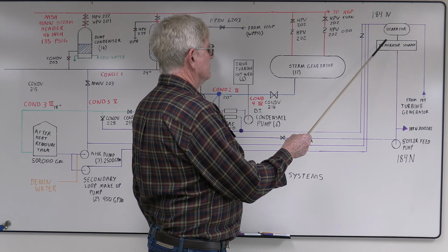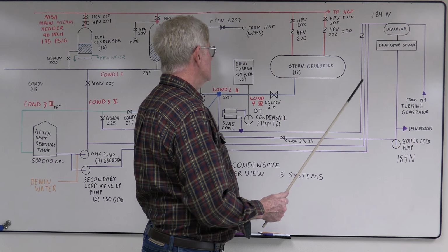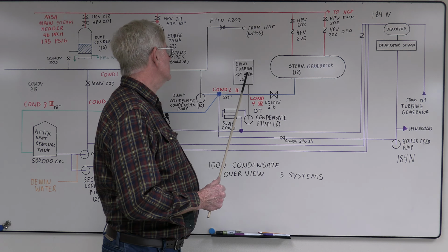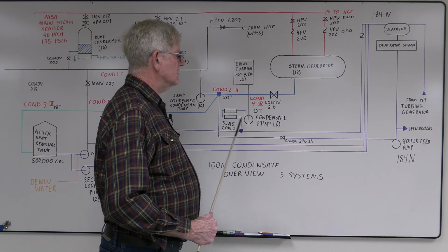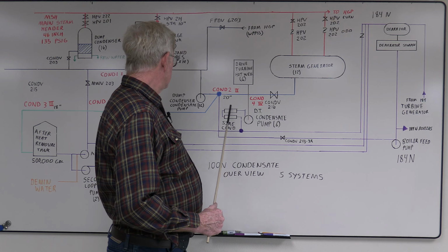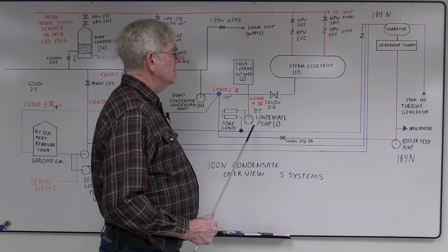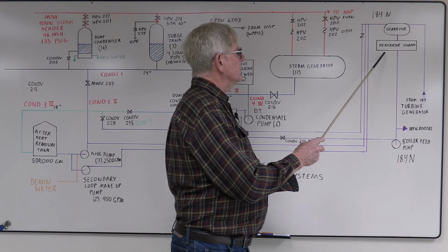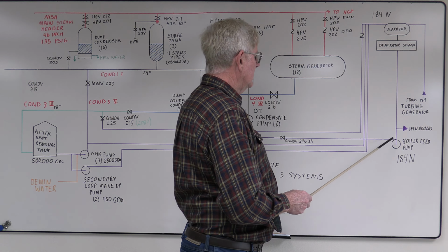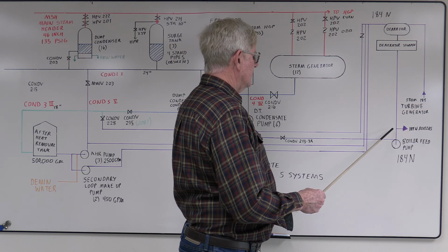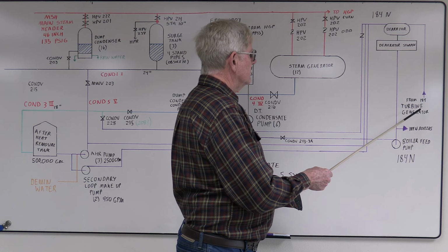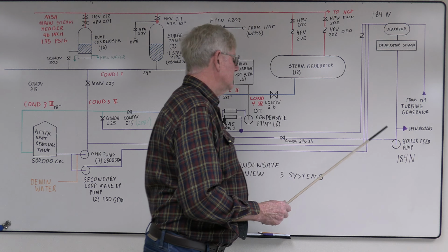From here, Condensate 5 went up to the deaerator in 184 powerhouse. It fed the deaerator. It took out all the dissolved oxygen. As you're pulling a vacuum, you'll pick up air coming into your drive turbine and pick up oxygen in the water. So after you go through a steam turbine dumping into a vacuum, you want to deaerate it. Water's deaerated, went down to the deaerator storage tank, went down to the boiler feed pumps.